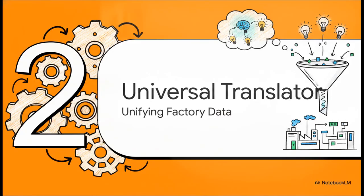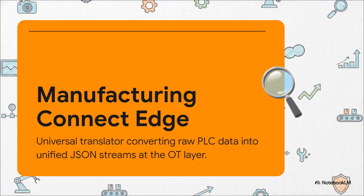Section 2, MCE, the Universal Translator, Unifying Factory Ingestion. Enter Google Cloud's Manufacturing Connect Edge, or MCE. You can really think of MCE as the ultimate factory floor interpreter. It operates right there on a modern industrial gateway, connecting directly to the physical PLCs at the OT layer. So instead of leaving you stranded trying to figure out what to do with all that chaotic raw register data, MCE standardizes it. It takes those raw streams, whether they're coming from OPC UA, Modbus TCP, Siemens S7, or Ethernet/IP, and converges them into clean, structured payload formats, specifically a unified, normalized JSON stream.